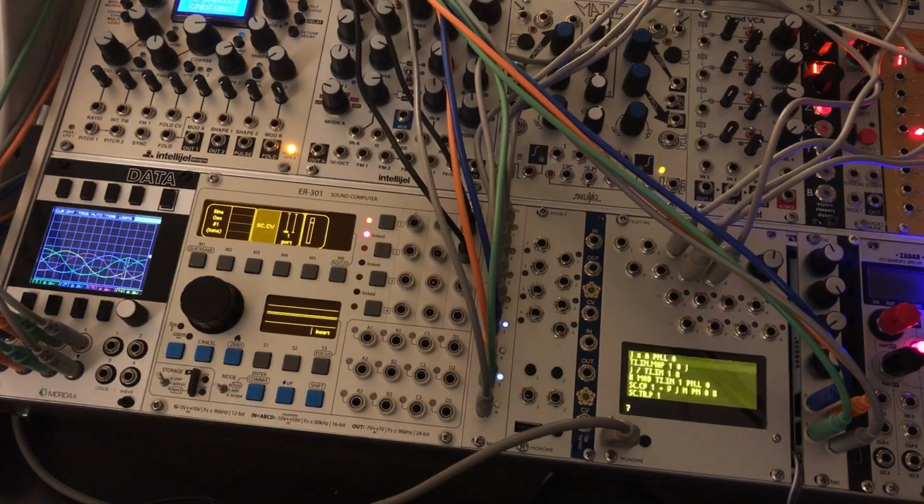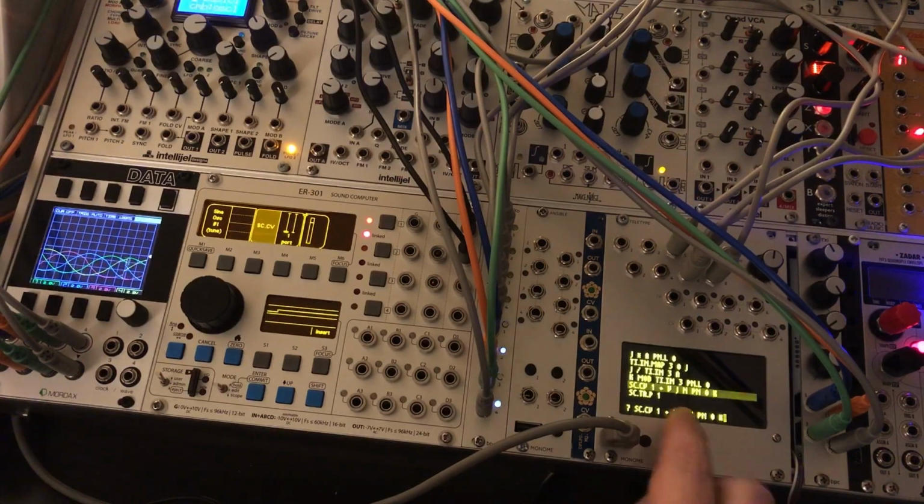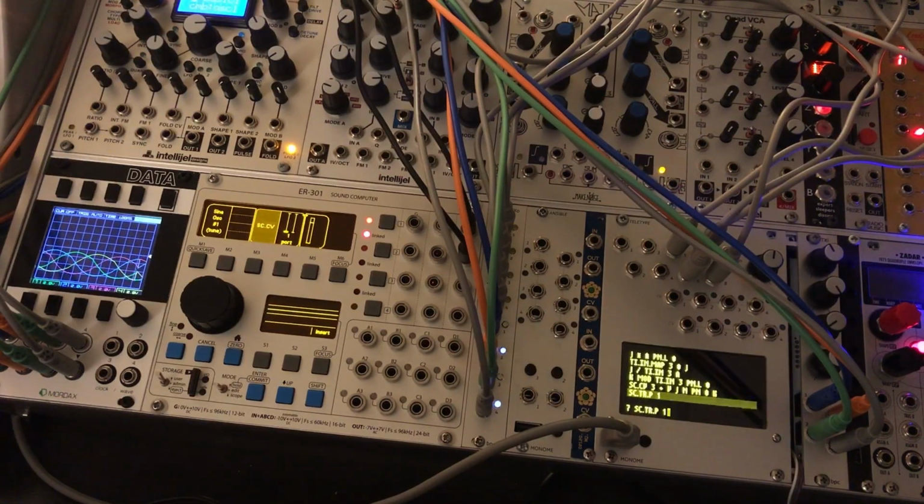Alt-V to paste these lines in, and again, we'll just change the references. This first line is still good. Here we're going to map TXI input 3. We're going to reference TXI input number 3. TXI input number 3. Here we're going to change the CV voltage port to 3 and the trigger port to 3.